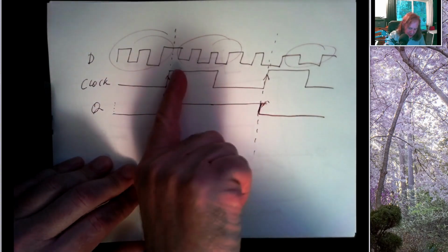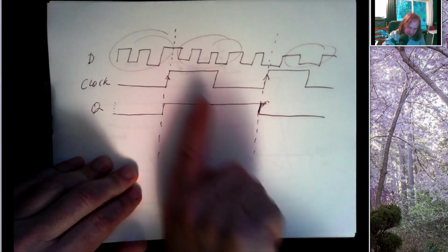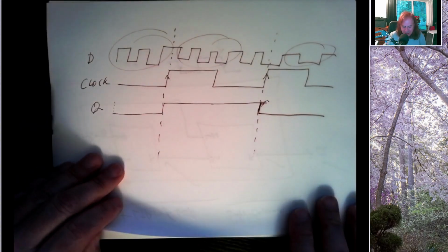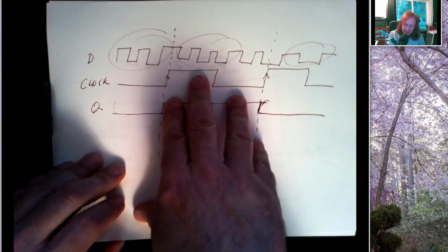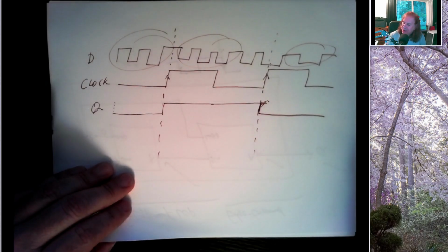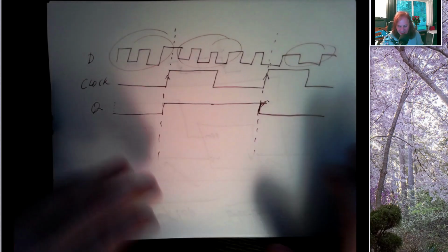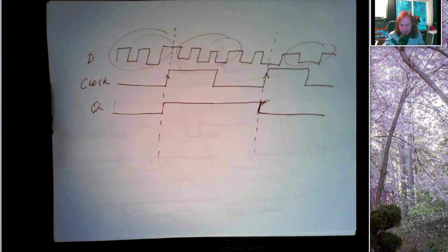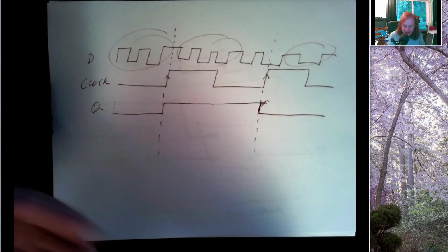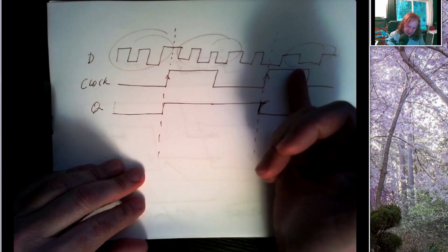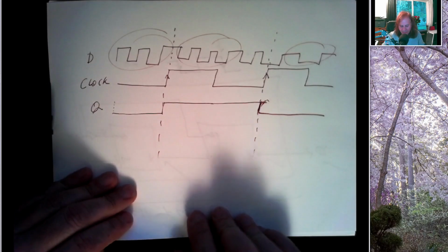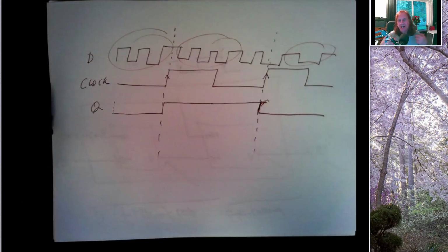And basically, in between each of these clock ticks, the positive going edges, things can be changing, but they're mostly ignored. That's when the circuitry inside the machine is taking time to adjust to a new state. Inputs are moving through circuits and causing outputs to change, and then everything should stabilize by the time the next clock tick happens right here. And now a whole bunch of other things change, and all of that change stabilizes, and then the next clock tick happens.